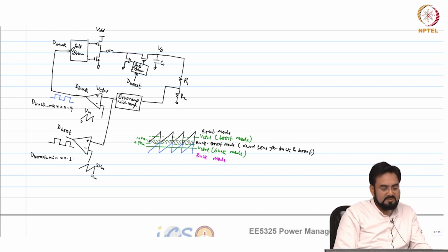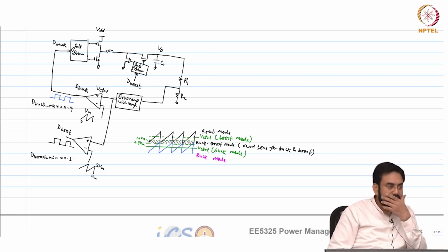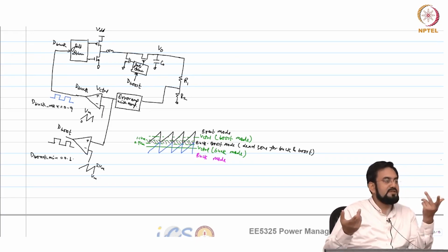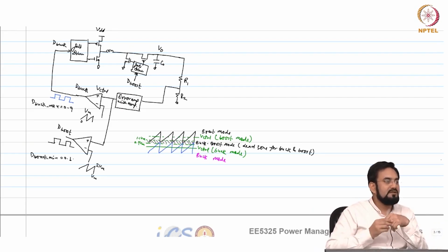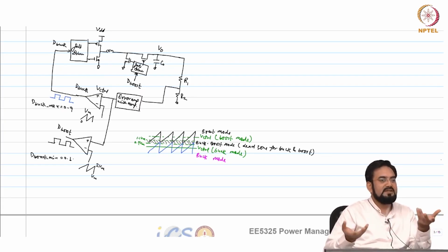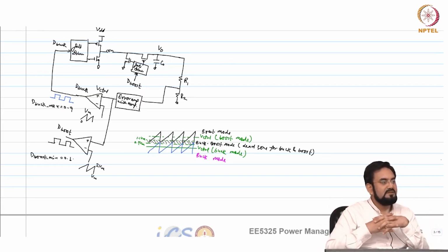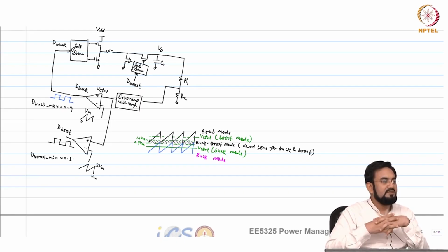So how will it operate in buck boost? How will you build that control? So I have only 2 options, 0.9 and 0.1. I mean 0.9 buck, 0.1 boost. I cannot get anything in between that. So what are the possibilities if you have only 2 duty cycles? How can you still regulate the output with only 2 duty cycles? We talked about it.